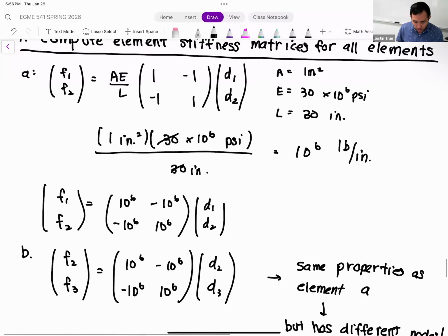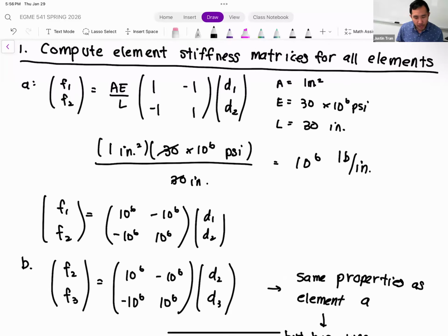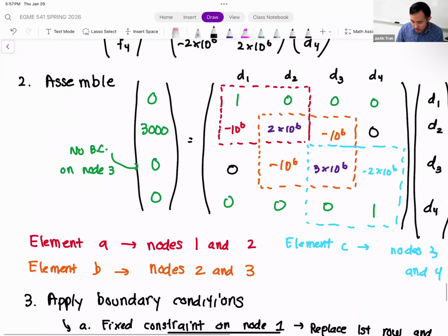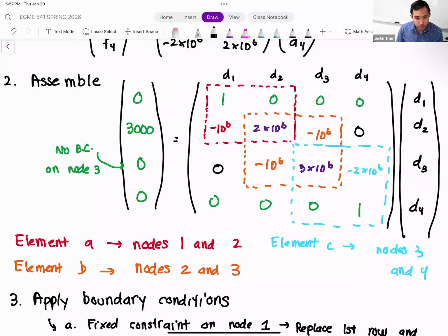Okay. And so ideally, in most problems, you're going to have numerical values for all of these quantities, right? Once you insert the numerical values and you just have the matrices, from there, we've kind of forgotten, or it doesn't really matter what our element types are. They're just numbers and matrices, and they're attached to nodes at that point. So, once you get to the assembly step, if you have springs, you just plug in whatever value you get from the spring constant, and you make sure you plug it into the appropriate place here.